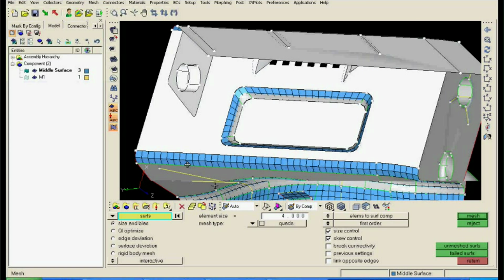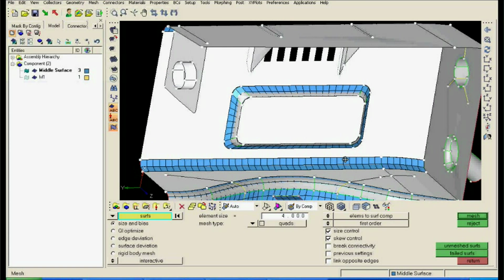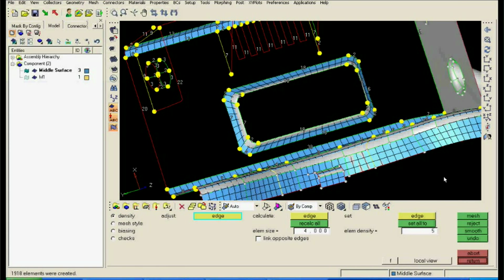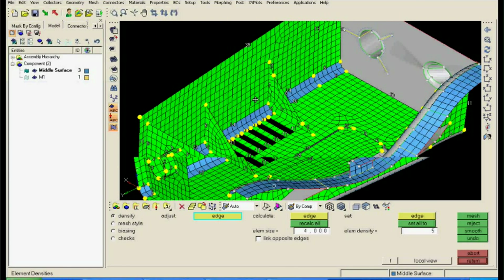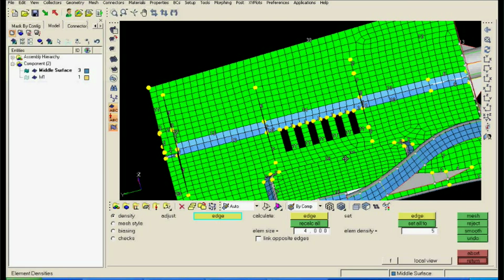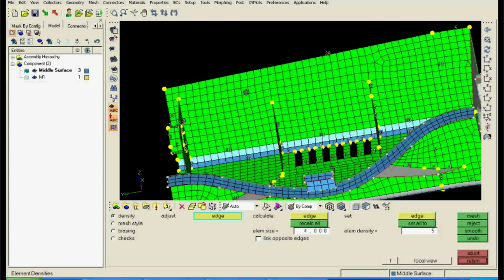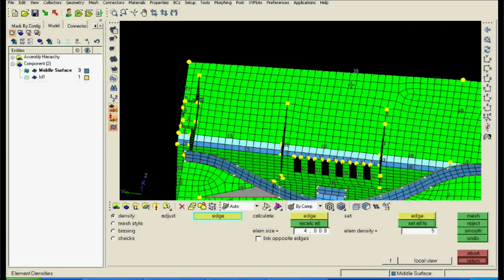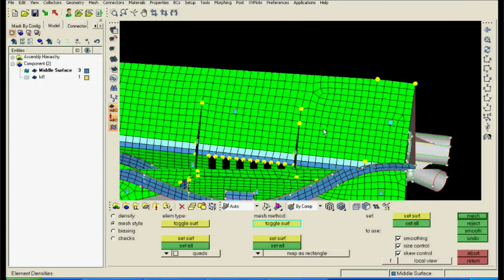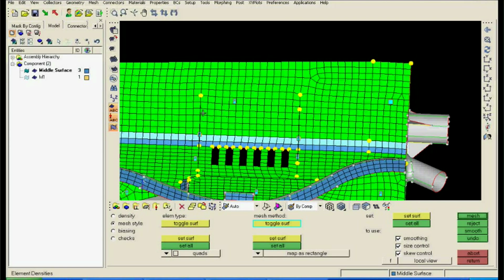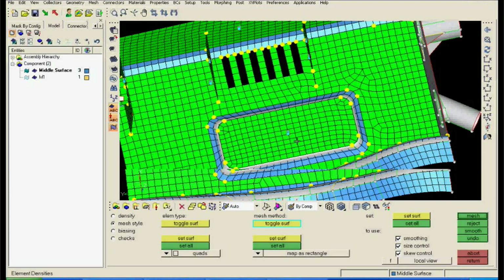So you can see this is a good mesh pattern again, and you can see why I created that cut line here. Because of that cut line, now you have such a nice mesh pattern. Without that, one can also mesh, maybe you can get a little bit of free area on this side, but again there is no such rule that one has to do that. One can afford to even have something like this. So that is what I said, that this more or less depends on the kind of one's wish and experience.